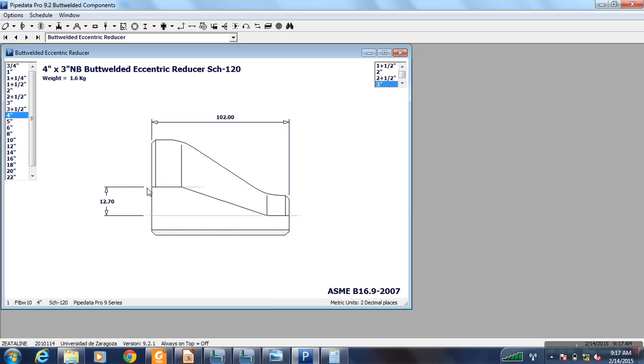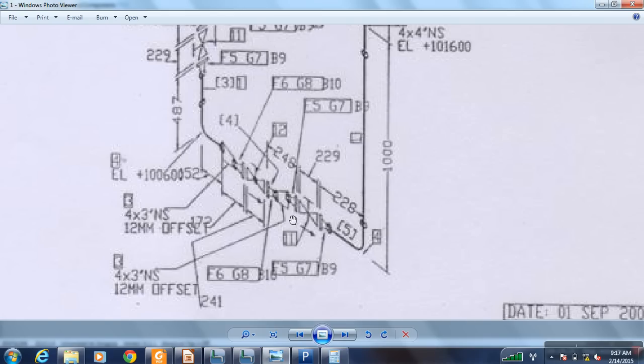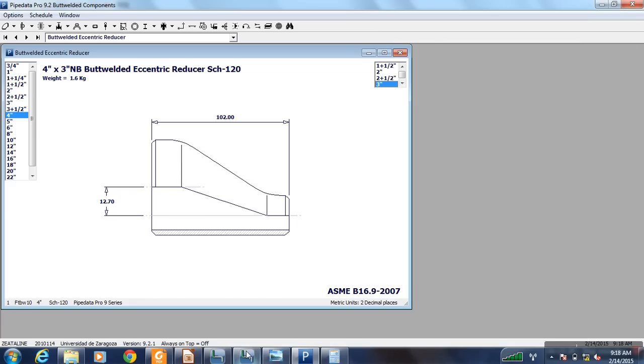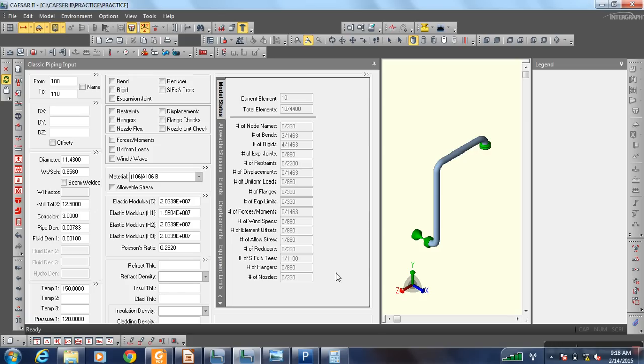That was the center for this, the total nozzle. That was the center for this 4 inch, and here it was the center for 3 inch. The axes of these two centers are varying in terms of length. Now the length for this reducer is 1. Here it is given as reducer plus flange dimension. Now we are drawing a reducer, so it's in the minus x direction and the dimension is minus 1 0 2.